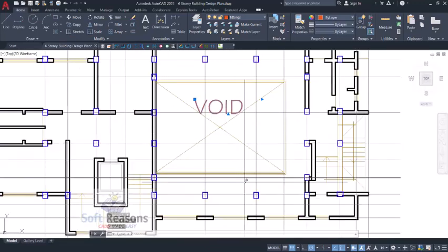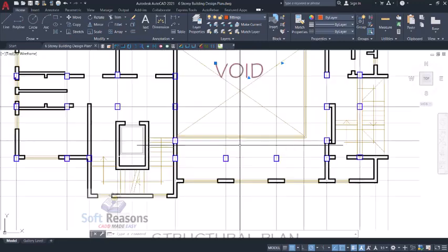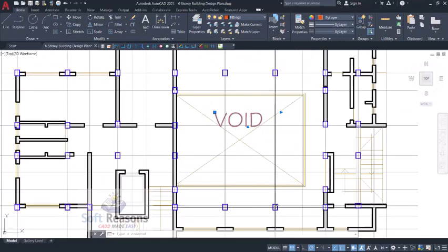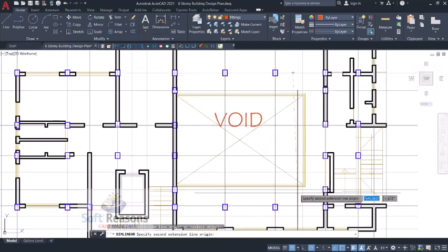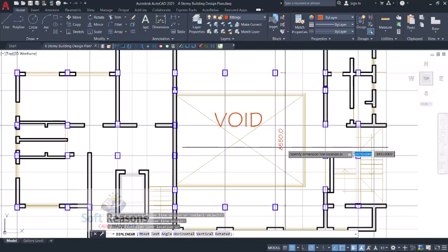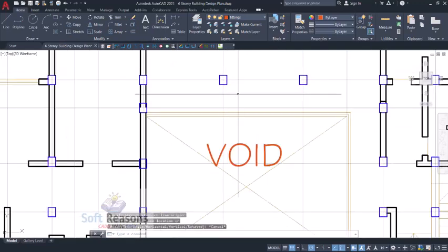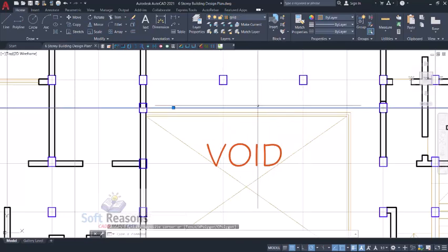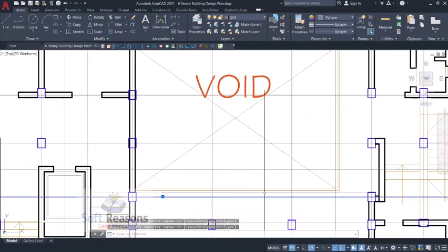Okay, I actually provide this vault because over on the second floor there will be a beam that will actually run from this column to this column. So if you check very well with your dimensions, you will see that the beam length is going to be 8.5, and this is going to be a very deep beam. All right, so to get rid of such deep beam, we need to place an additional column at this point, along this grid line. Okay, and as well along this grid line successfully.